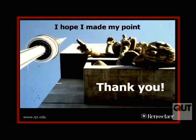The work that I'm doing here is with CASE, the Centre for Architecture, Science and Ecology, and their work is really about a holistic approach to tall building design. So not only looking at indoor and external air, but also lighting, shading, and energy flow in and out of the facade. It's part of an integrated package of improving the interface between the external and the internal. This was just one aspect of it, where we did have air being exhausted. Could we do that in a more efficient and effective way for looking at aerodynamic response? We certainly demonstrated that it's possible to change the flow with the volumes of air that we needed. It may not be enough in the design case, but that can be modified down the track.